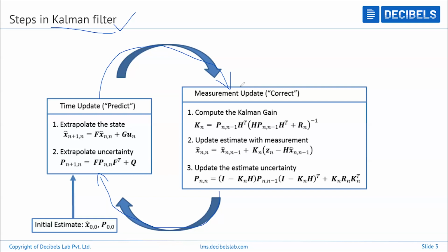In terms of the maths involved, the linearization of your states matters a lot when it comes to the application of EKF or UKF. There are different methods like Taylor's and Jacobian methods.